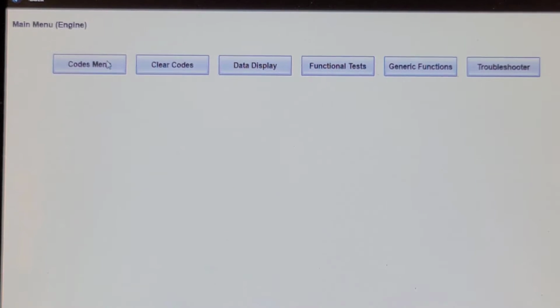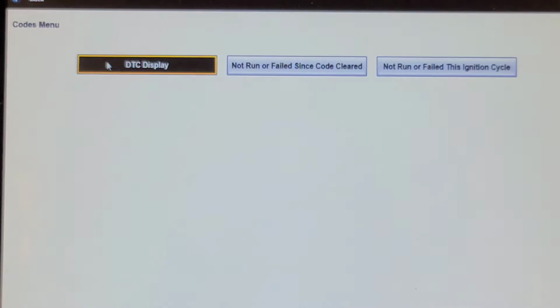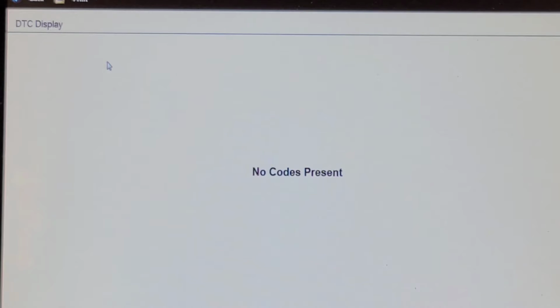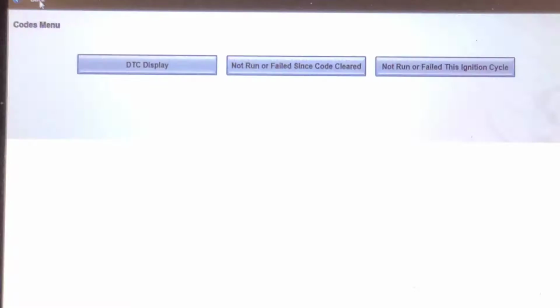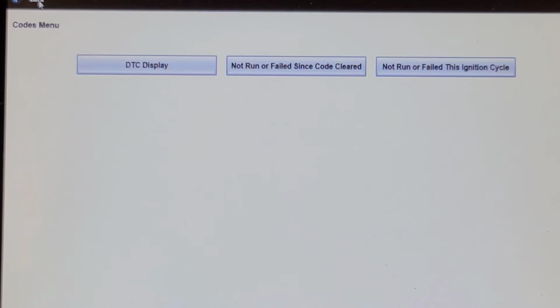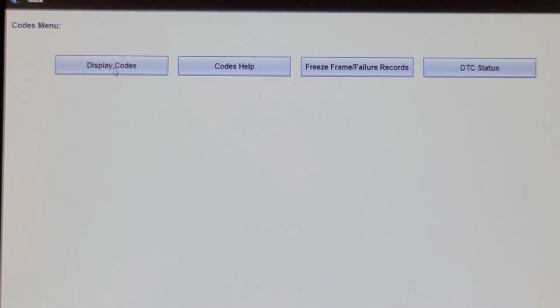Give it about 5 seconds. If there's a problem in the wiring, it should, see, you gotta love it when the scan tool lies to you. I'm going to check the continuity through that solenoid now instead of wasting time testing the circuit, because the code has gone away with the test light installed.